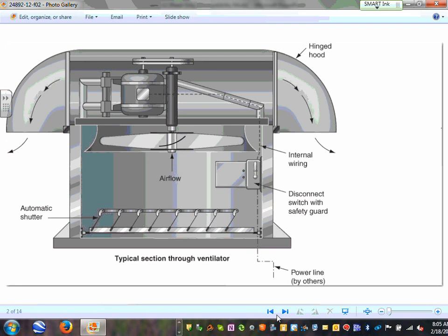To summarize, guys, this is about chillers and exhaust fans. Exhaust fans are motors, easy, electrically speaking. We need an overcurrent protection device and a conductor to them. Chillers, same thing, very easy. We need an overcurrent protection device and a conductor to feed them. The controller, guys, typically the controller, as well as the overload, as well as the disconnect, is provided by the manufacturer for these. Unless they tell you otherwise, they're provided.